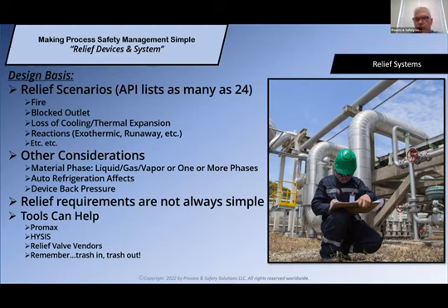There are tools like Promax out there that you can use to help you model the various relief scenarios. There's HYSYS that can be used. Even some relief valve vendors can help you with the sizing process once you've provided them the information on what your requirements are. Remember, trash in, trash out.